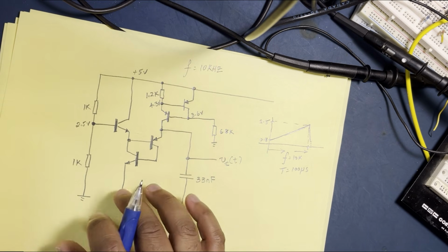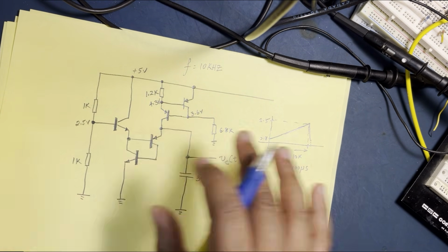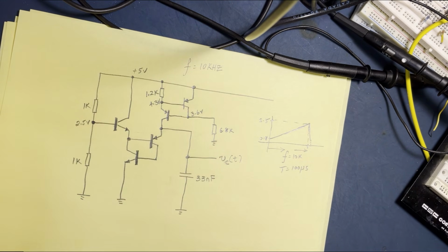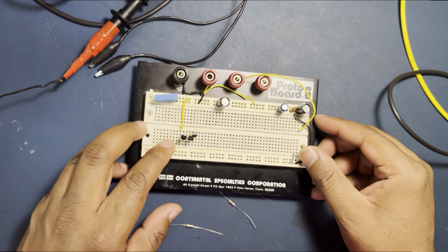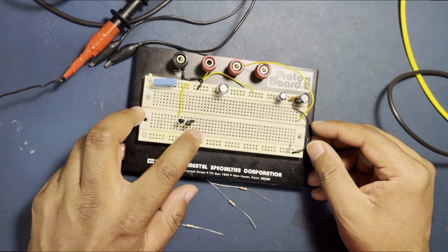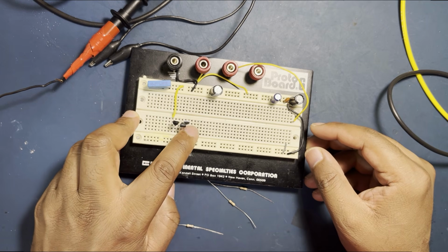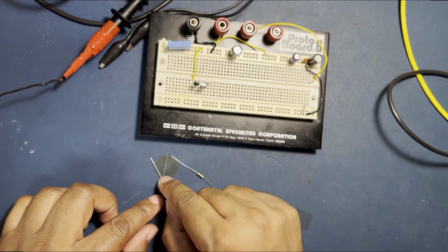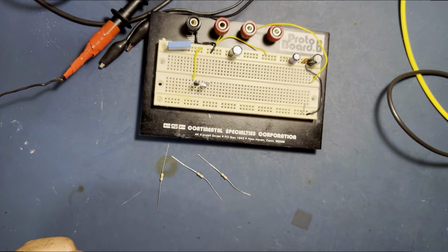Give me a second to build the circuit, and we'll use an oscilloscope to measure the frequency, look at the waveform, and use a meter to measure all of the voltages. Okay, the process of building it. So basically I've got my emitter follower transistor here, the two NPN and PNP back-to-back connected switch transistors here, my two 1K resistors and 6.8K resistor ready. So just keep building it.